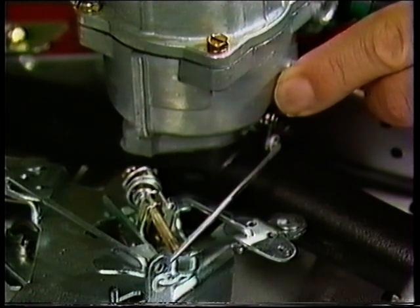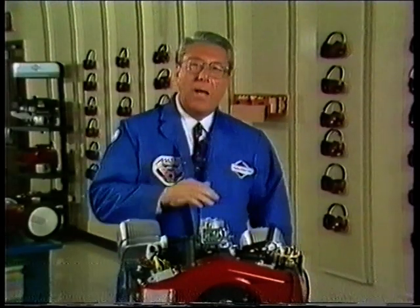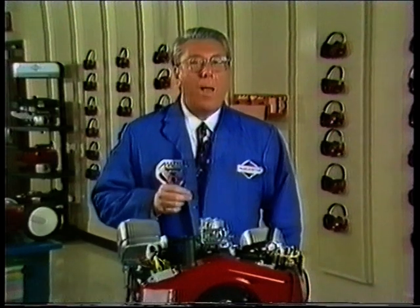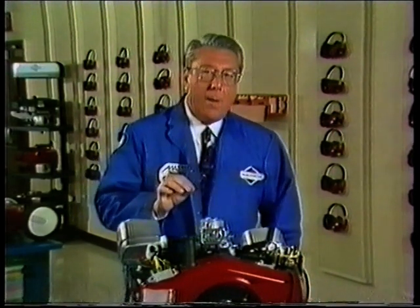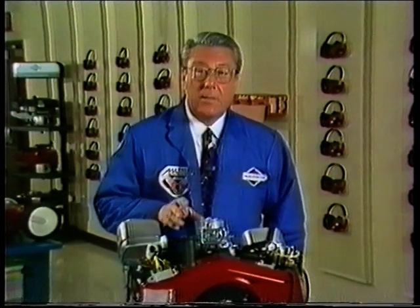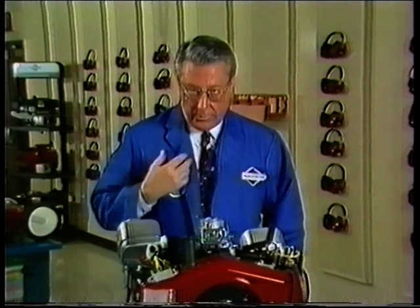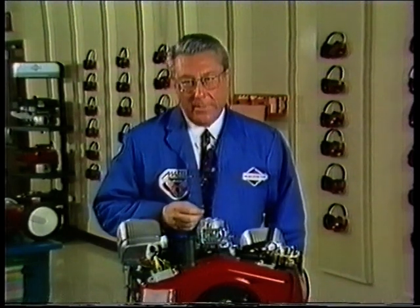Don't forget to readjust the idle speed screws to specifications. What if the engine hunts and surges only under a load? In this case, the problem is nearly always the carburetor. Why? Because when the carburetor delivers fuel under load, it feeds fuel almost exclusively through the main nozzle. Once the engine is loaded or doing work, the governor system has little additional effect on performance.